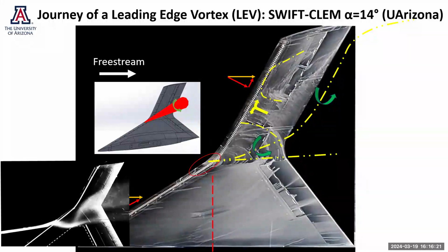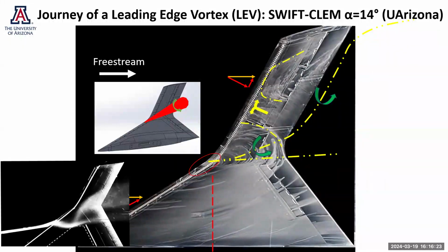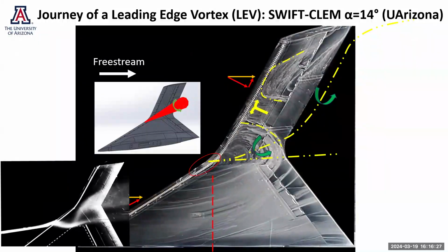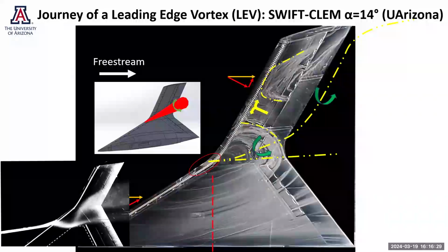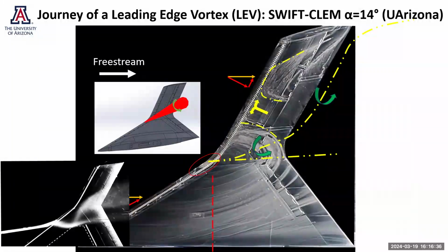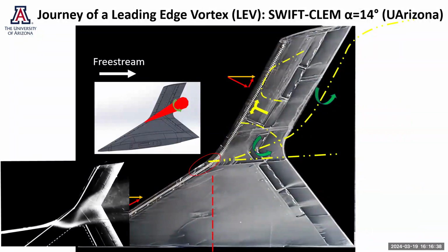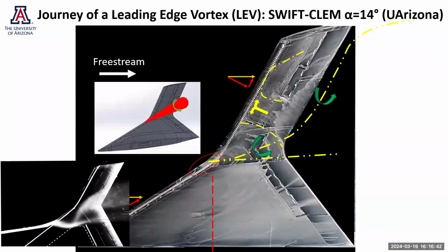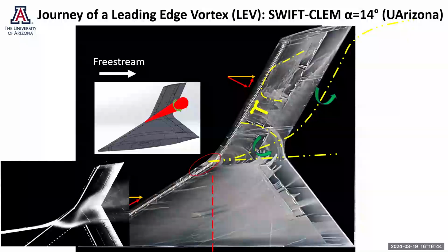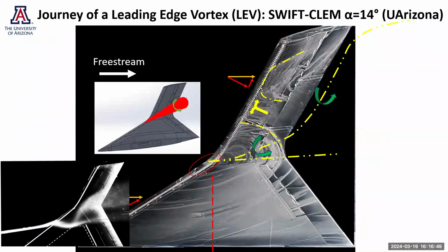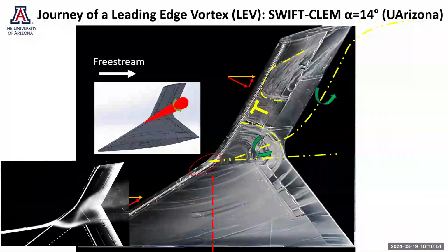But when we were looking at a different wing, we did see that a long time exposure picture with smoke impinging on a similar geometry wing revealed a bimodality of this vortex liftoff process, wherein part of the smoke goes streamwise and part of the smoke goes spanwise and then streamwise. So we hypothesize that even on this model, we may see a bimodality of this vortex liftoff.